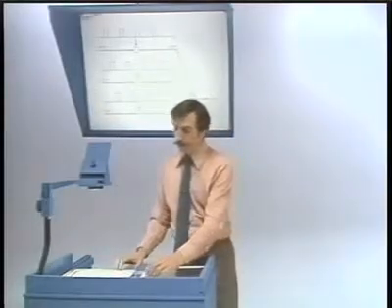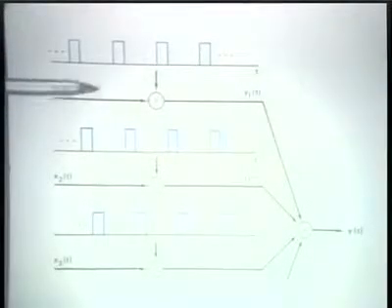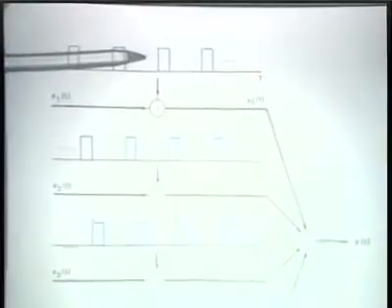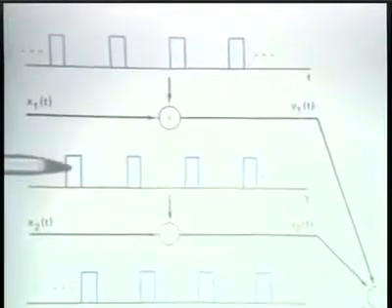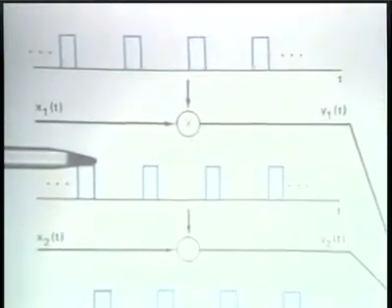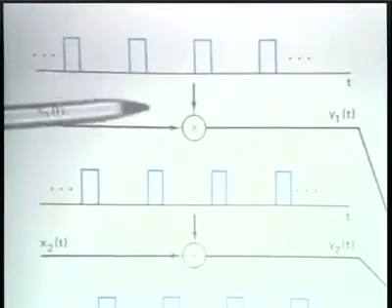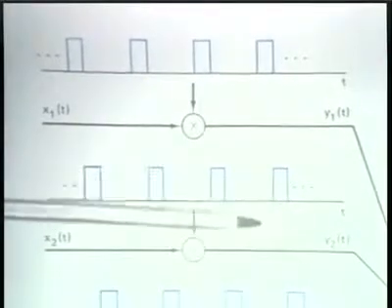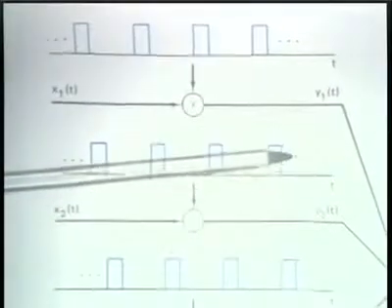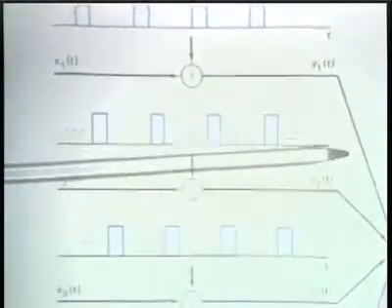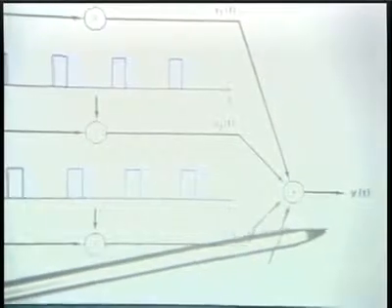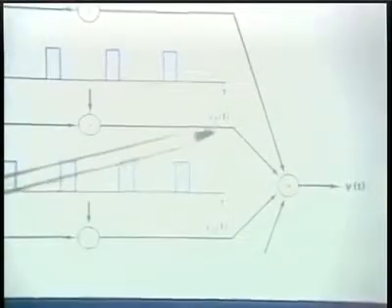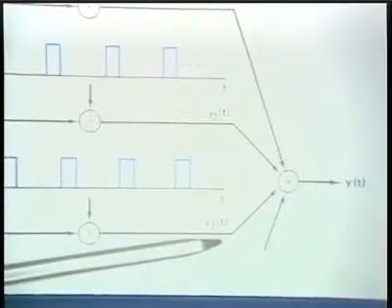So in particular, suppose that I had a signal which I modulated with a pulse train, and I chose another signal modulated with another pulse train where the time slot was different, and I continued this process, and after I've done this with some number of channels, simply added all those together, as I indicate here, then as long as I knew what time slots to associate with what signal, I could get the original modulated signals back again.